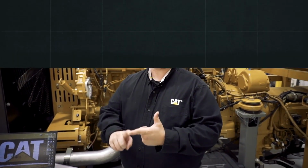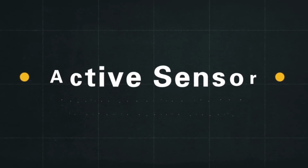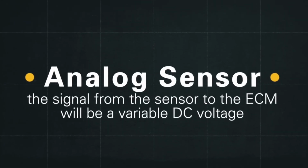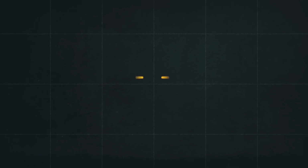Before we get too deep into the troubleshooting, I want to make sure we understand when we say active analog sensor, what does that mean? Okay, active sensor. An active sensor requires power from the ECM in order to operate properly. In this case, we're dealing with a 5-volt sensor. Okay, analog sensor. What does analog mean? Analog means that the signal from the sensor to the ECM is going to be a variable DC voltage that is going to change based on the parameter being measured by the sensor.